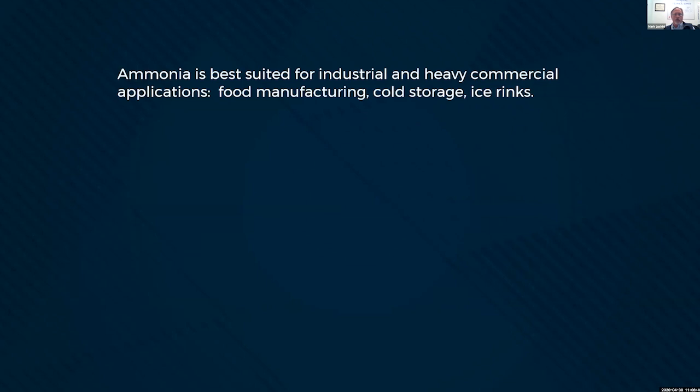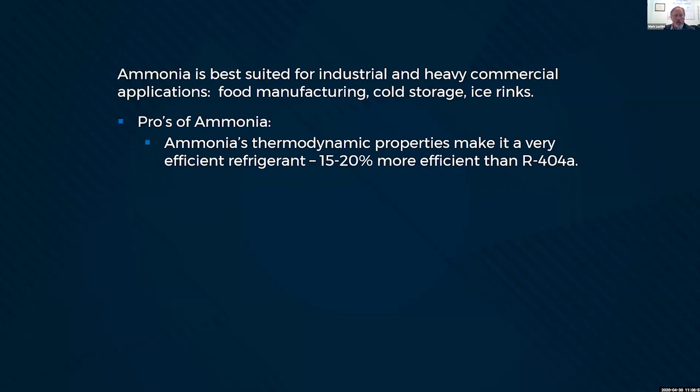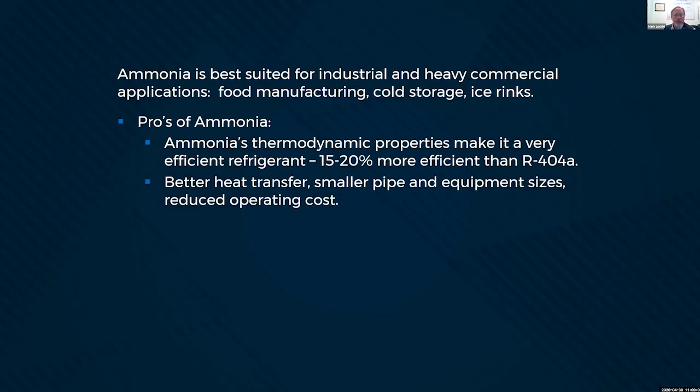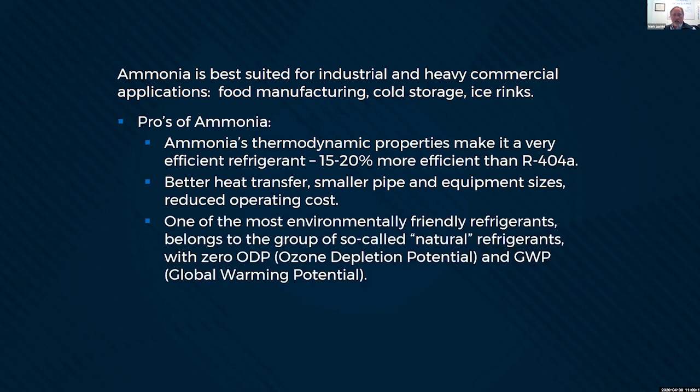I mentioned ammonia before. Ammonia is a very good refrigerant. Actually, it's best suited for industrial and heavy commercial applications. I don't know if they got used down at Boston Sword, but it wouldn't have surprised me if some of their stuff was ammonia driven. It's got some good qualities. It's very efficient thermodynamically, so that leads to better heat transfer, which allows for smaller piping and equipment sizes, and also reduces your operating costs.